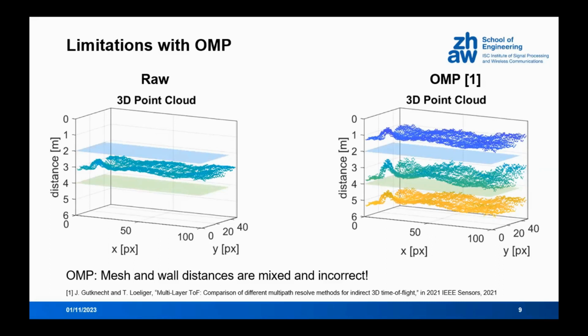And when these two vectors or measurement distances, for example these 2 and 4 meters, are close together and have roughly the same amplitude, they are merged together and we only measure one distance. Therefore, the distance at 1 meter and the distance at 5 meters are just additional errors because the algorithm wanted to compensate for the error it made in the first place.